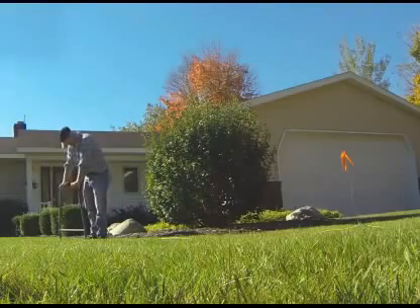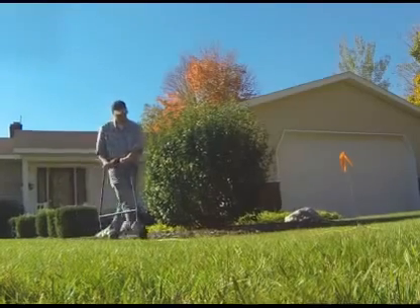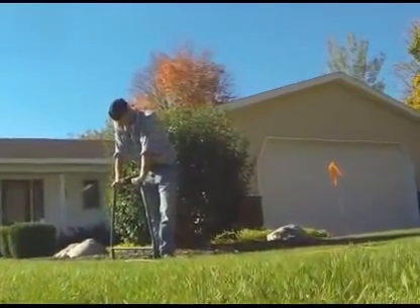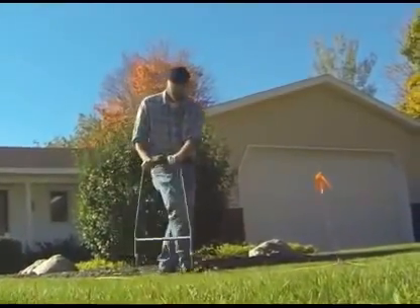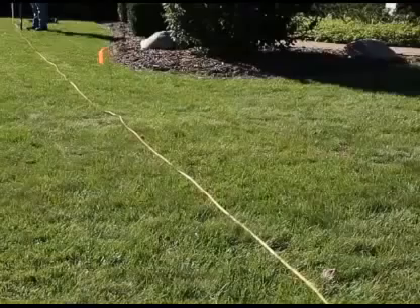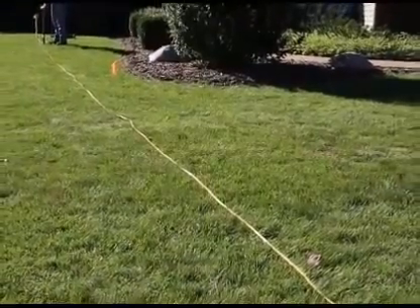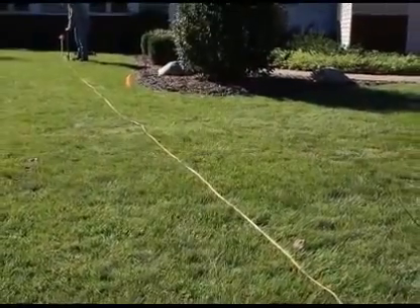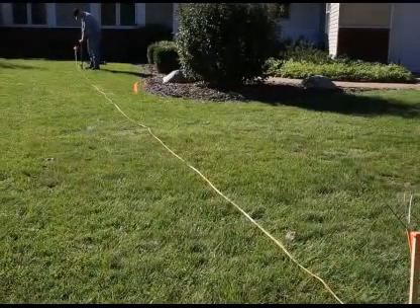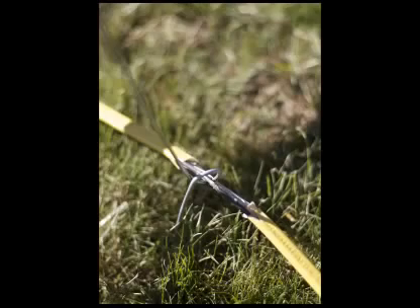The GFL 3000 is designed to pinpoint the exact location of a ground fault in a cable. The GFL 3000 is not intended to locate the entire path of a cable. To effectively pinpoint the location of a fault using the GFL 3000, the path of the cable must be previously determined and the wire must be in direct contact with the earth.